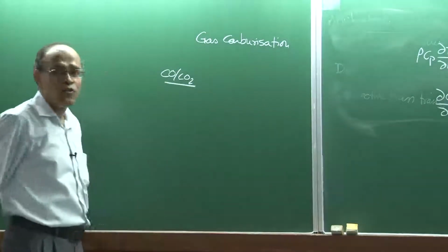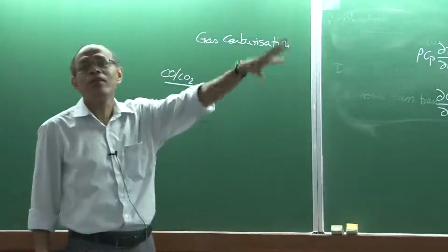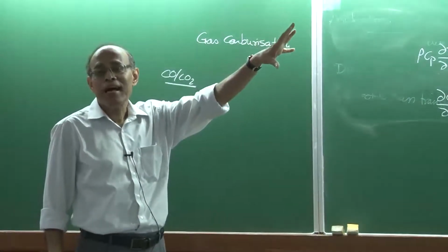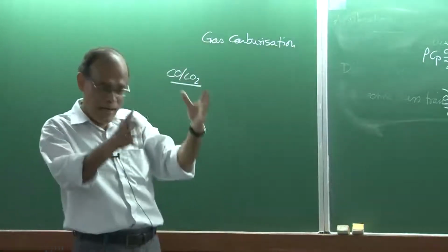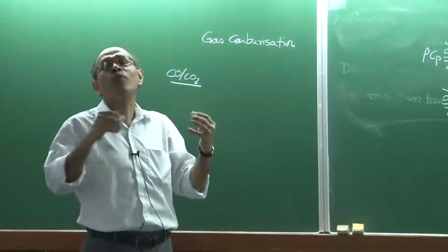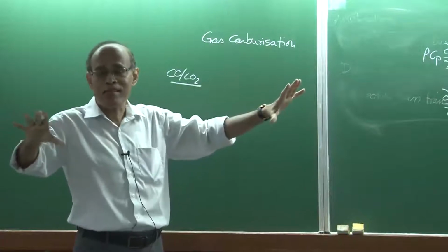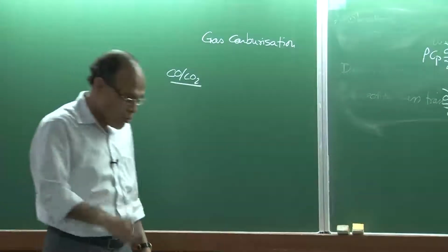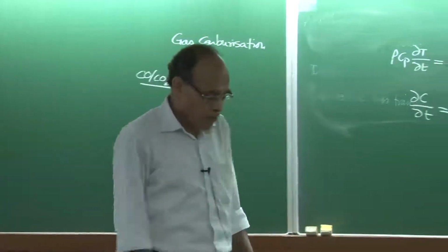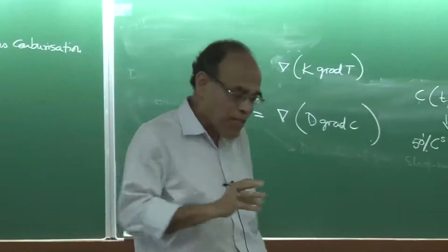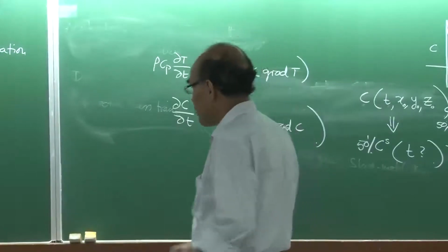That is the gas that you use, and that gas you pass over the steel solid sample at a high temperature. Okay? So you can keep the sample in a furnace at 1000 degrees centigrade for a prolonged amount of time till it is homogeneous. Now you start to pass a carbon monoxide, carbon dioxide mixture over that solid sample.